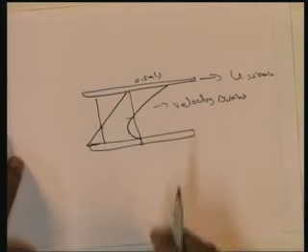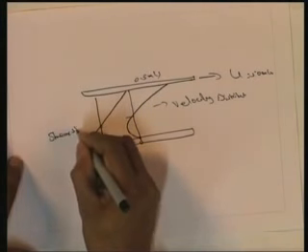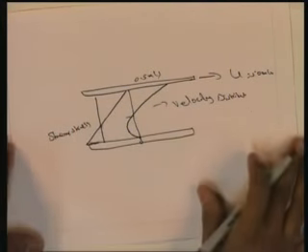So this is the variation of shear stress. From this expression we can find the variation of the velocity and the variation of the shear stress. Like this, various problems with respect to the Couette flow, where one plate is fixed and the other plate is moving, we can solve.